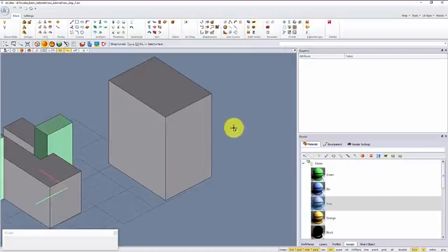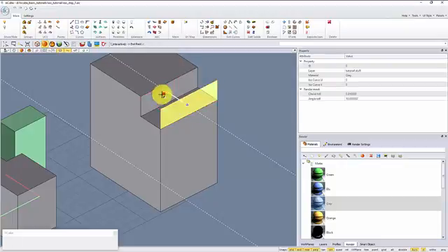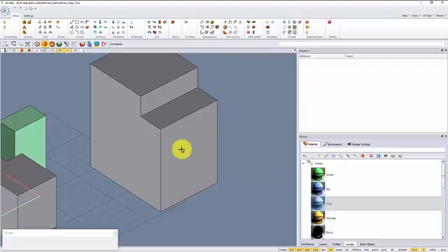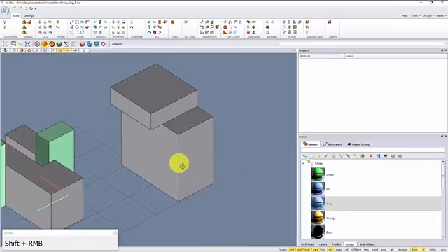The drop curve tool asks for a face and will extract from the face a parametric curve in the U or V direction. So you see, the red curve is the curve that we are going to extract. You click and the surface is split again by the parametric curve. If I repeat this tool, you can flip the direction of the curve so we can get another curve, drop it on the surface.